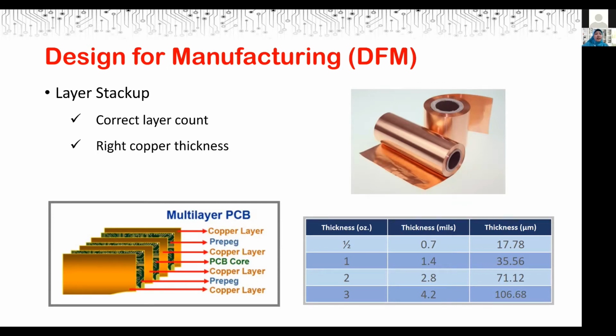And then we also have other layers such as solder mask and silk screen. So copper foils here are shown in this kind of format. They are actually in rolled coil foil. They are rated in ounces from ½ ounce all the way to 3 ounce.